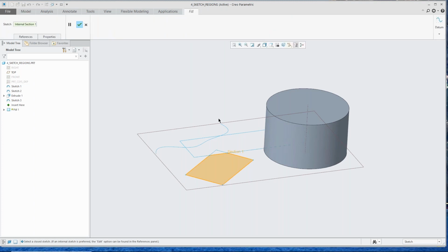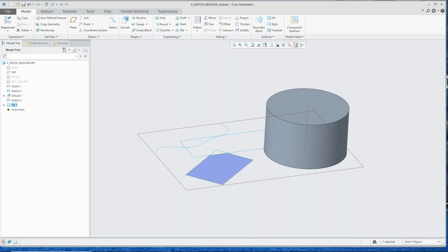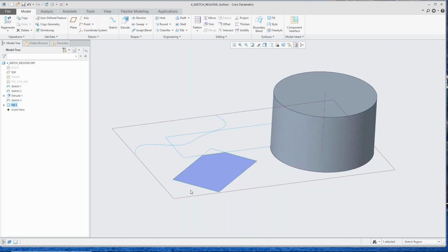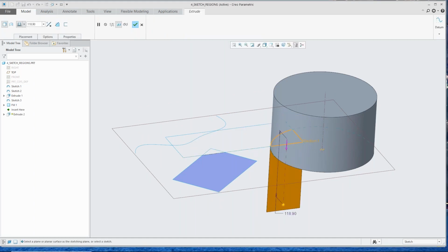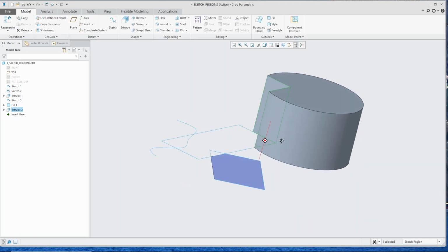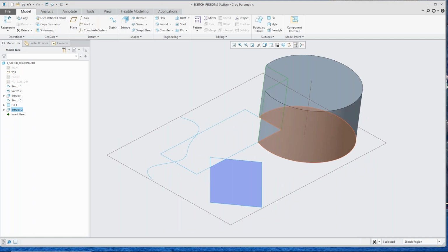Here I have a folder, and I'm saying file open, and we see nothing listed here. So I'm going to go under here and say search. And I'm going to go down here and say, let's look for Inventor files. So there's an Inventor file there. So I'm just going to say open it up. And it brings it in in its native format without converting it or anything like that.